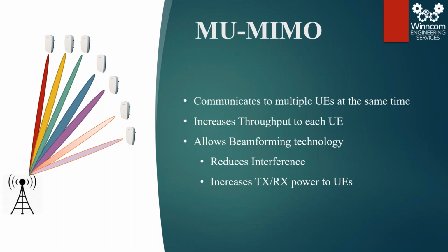So how it basically works is your antenna will have a coverage of 140 degrees. It's not radiating for that entire 140 degrees. It's just there. And then when a UE sends a signal, the sector will see that it's there and it'll form a tight beam. And that's how the beam forming works for MU-MIMO.